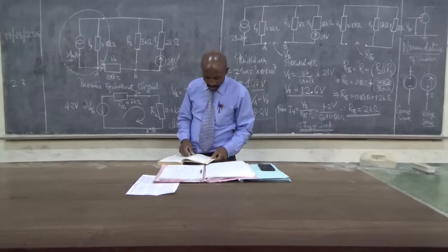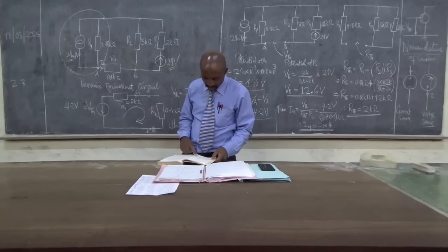A second form of equivalent circuit useful in situations as, for example, transistor circuits where current sources rather than EMFs have major interest, is one given by Norton's theorem, which states that any network of batteries and resistances having two output terminals can be replaced by a parallel combination of the current source and resistance RS.